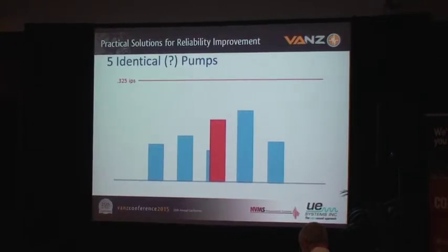But the interesting part about it was, as you can see in this chart, even though the number 3 pump increased by a factor of 2, its problem amplitude was still below the amplitude of the number 4 pump. I called the control room. During this particular time of year, we did not need to run all 5 pumps simultaneously. We were only running 4 of them at the time.